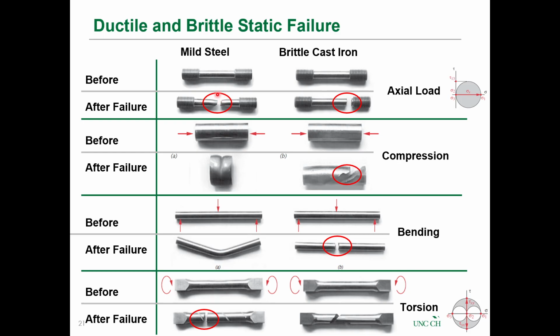And you see these are opposite, okay, for the ductile material. When you apply the axial load, you get failure in the shear plane. When you apply a shear load, you get failure in the principal plane. Versus a brittle material, when you apply that torsion, that shear stress, you actually get a failure mode in that shear direction. Okay, all right.